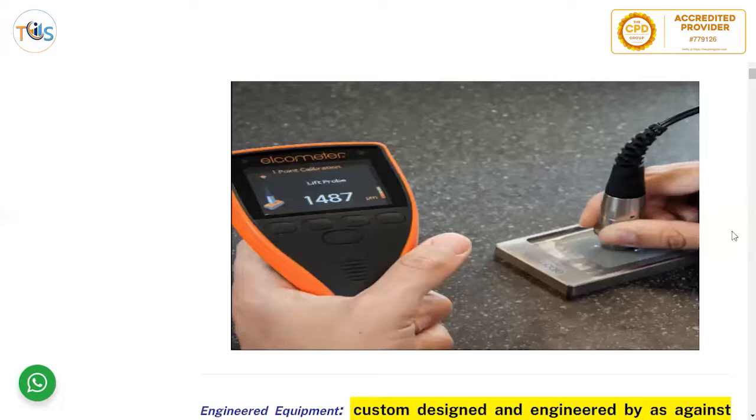Here you can see a paint thickness measurement gauge, and normally there are some shims or plastics with known thickness. You just calibrate it and see that it's actually giving the right reading, because you know the thickness of these shims. 2 or 3 different thicknesses you use for calibration, and then use it on actual material.